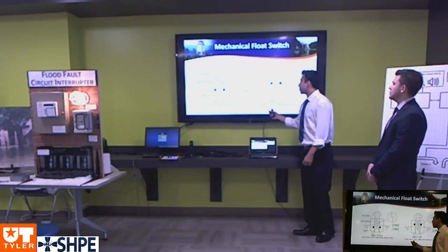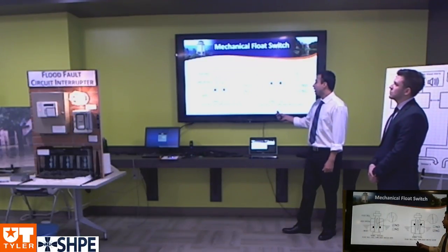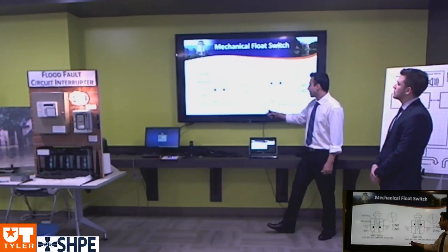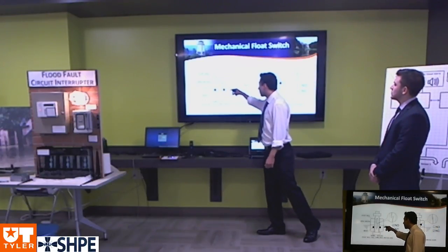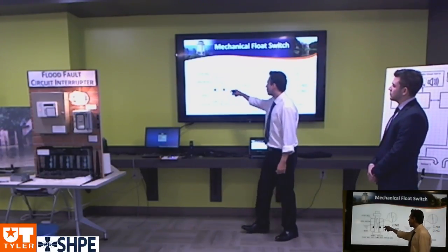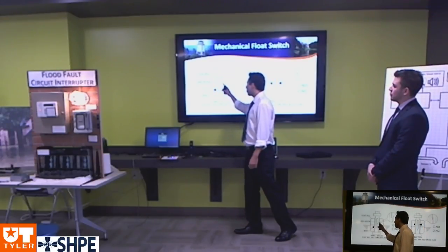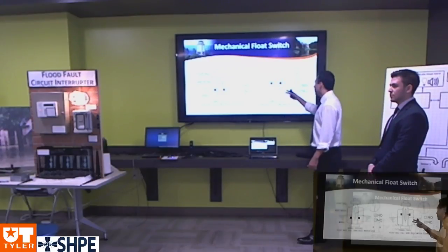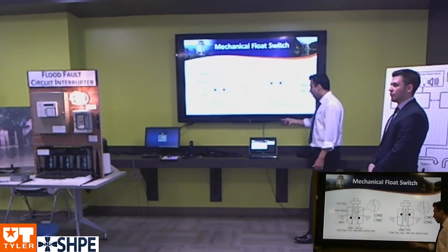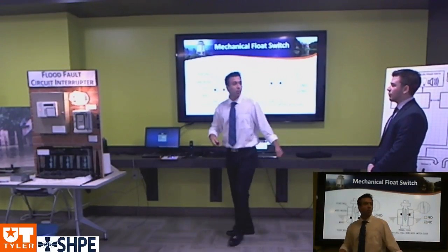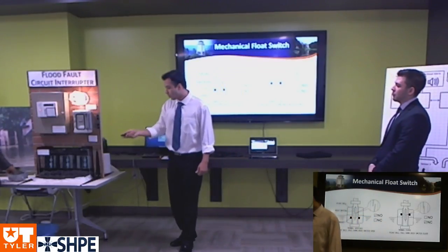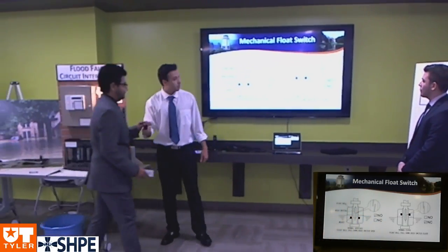So this picture shows the mechanism of the magnetic sensor. So as the water raises the magnets, there are two reed switches here, which are going to get magnetized, and as a result, there will be a connection, and a signal will be sent to our logic unit. Next, my team member will talk about the boxes that we created for our sensors. Thank you, sir.